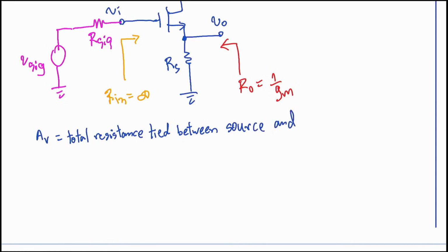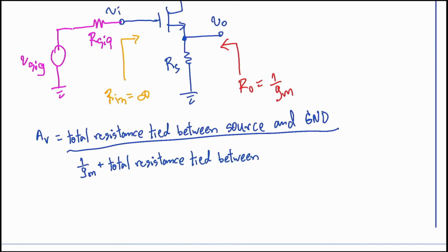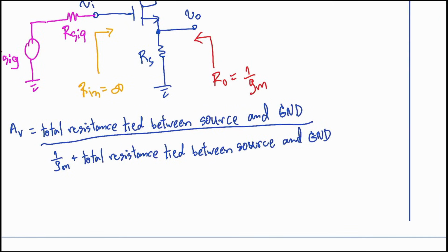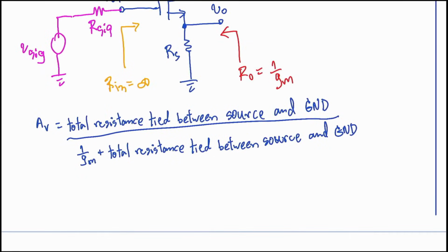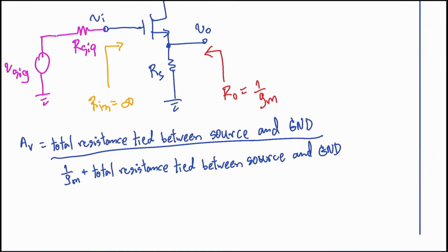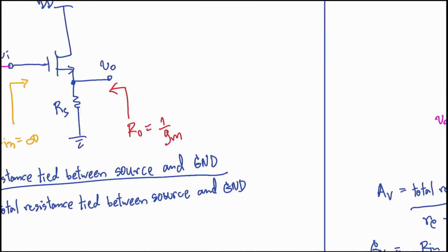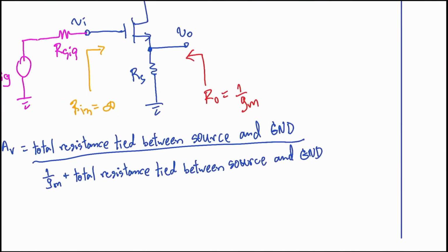Just now, I was trying to break this down for you because understanding this ratio is crucial for analyzing the circuit's behavior. Essentially, the gain is determined by this voltage divider-like structure where the source resistance plays a dominant role. By comparing these two, we can better grasp how the MOSFET operates in this specific configuration, which is a fundamental step in our analysis. Once you see the parallel, it becomes much clearer why we structure the gain equation this way to connect the load.